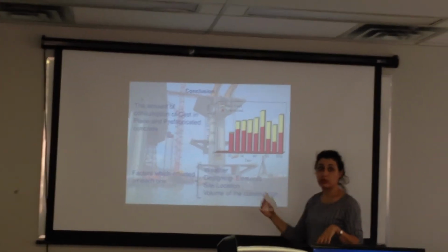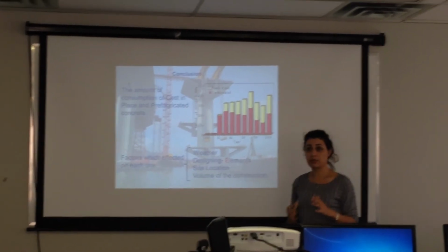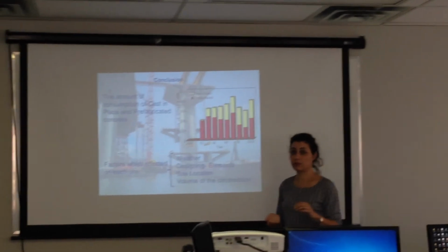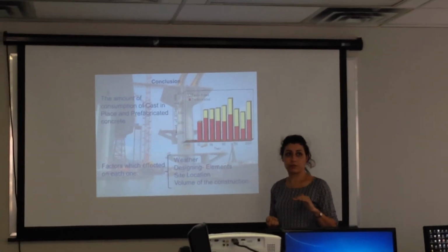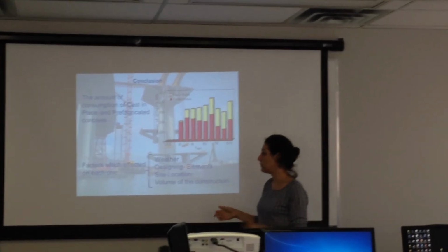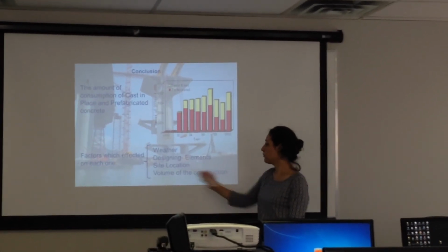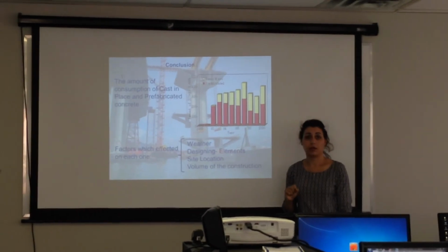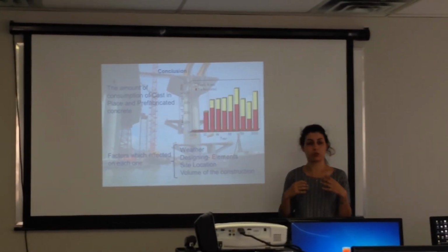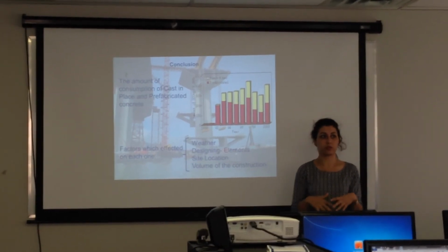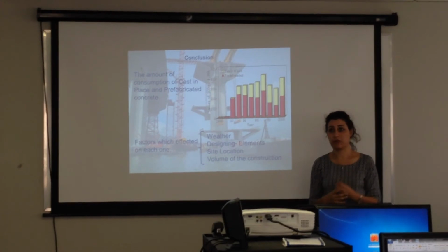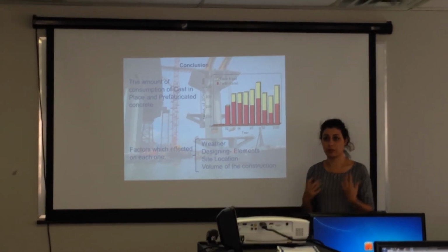The site location: if your site is close to the manufacturer of precasted, it's very good for you because it decreases the cost of the elements. And one more is the construction size. The precasted method is very good, but not for a small project. We can use it for, for example, a complex, and it's very effective and very logical to use.